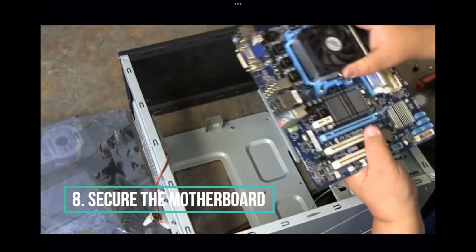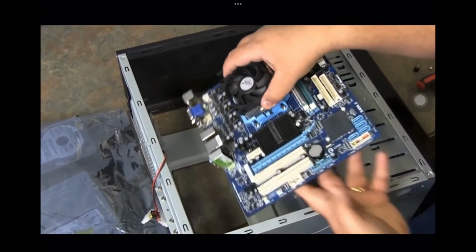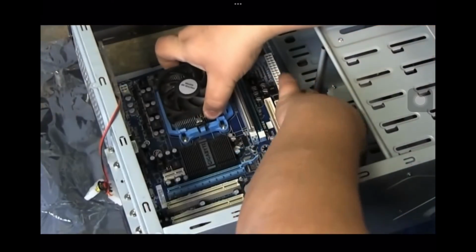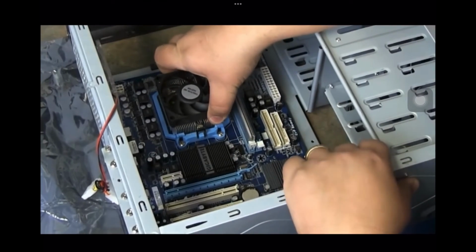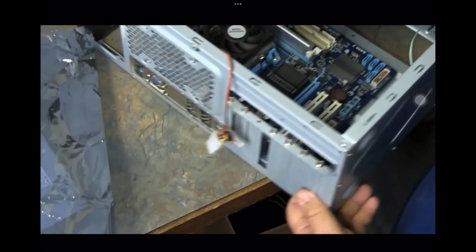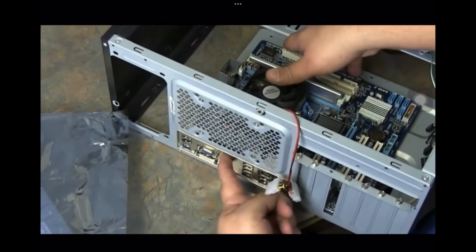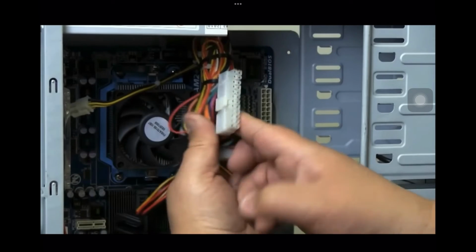Step 8 is secure the motherboard. Once the standoffs are installed, place the motherboard in the case and push it up against the backplate. All of the backports should fit into the holes in the input-output backplate. Use the screws provided to secure the motherboard to the standoff through the shielded screw holes on the motherboard.